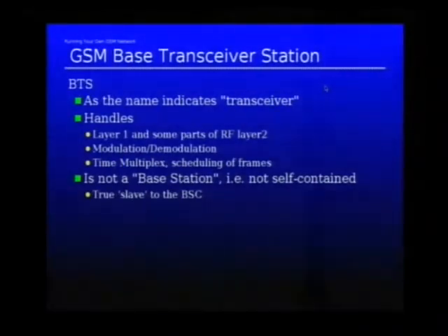It handles obviously the modulation, demodulation. There's an RF power amplifier. There's VCOs and so on and so on. The time multiplex, the scheduling of frames, these kind of things are done by the base transceiver station. But as I said, it's not a self-contained base station. It doesn't do anything by itself. The base station controller has to tell it everything.